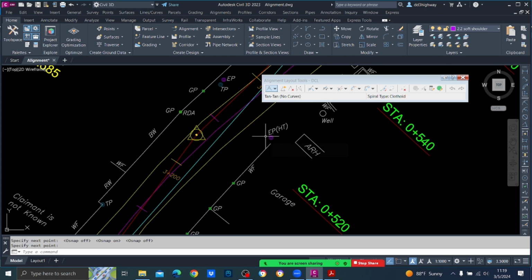So an IP you can only provide if the difference of the angle between these two tangents is lesser than 1 degree, or for 50 kmph, right? Now it is not lesser than 1 degree, you can see. And now we are going to provide a curve in between.